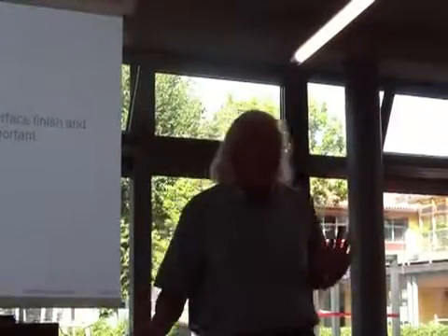We'll see tomorrow, it does matter in the choice of theories, whether you work in terms of stress or strain. But concept-wise, it really doesn't matter. It's in the input data. Anybody who runs stress-life testing worries a lot about surface finish, residual stresses from processing, and all those things.